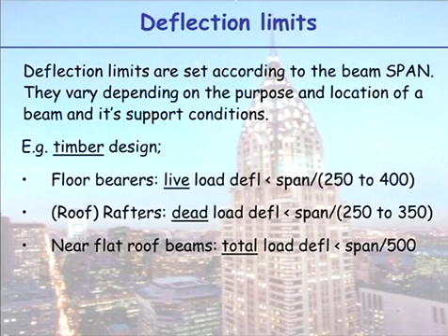Okay? So if you had a very big dead load deflection on a roof, the water will pond there and sit there and your roof will become damaged. If it deflects too much under live load, under wind load, well, who's up there to see that? So the deflection criteria is one for dead load. For a floor, because it's live load walking on your floor all the time, deflection criteria is live load.